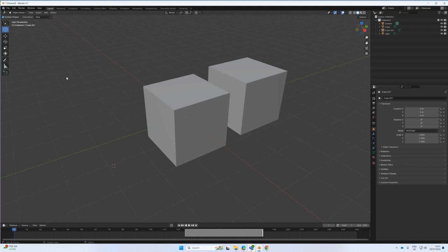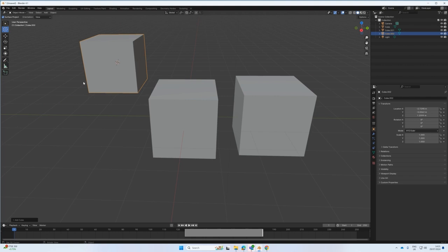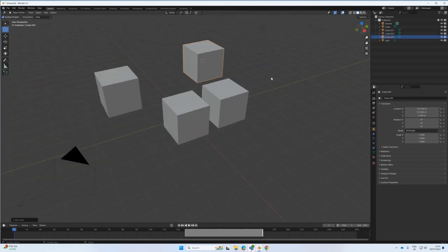Okay, let's say I'm going to put it here. So now it can be very useful. If I create a new cube now, it's going to put the cube where that cursor is. It's called the 3D cursor. So I have this selected. Mind you, anywhere you click is going to move it. So I'm going to come here and add another cube, and it's there now.